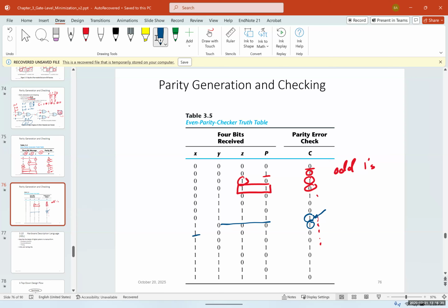If I have 1, 0, 0, 1, then I have the code is equal to 0, meaning but the ones that have a parity, which are 1s, you can see that these ones are creating most of the errors. So when initially we know that the parity code is 0 and suddenly becomes 1, we know that 1 bit is wrong at one point.